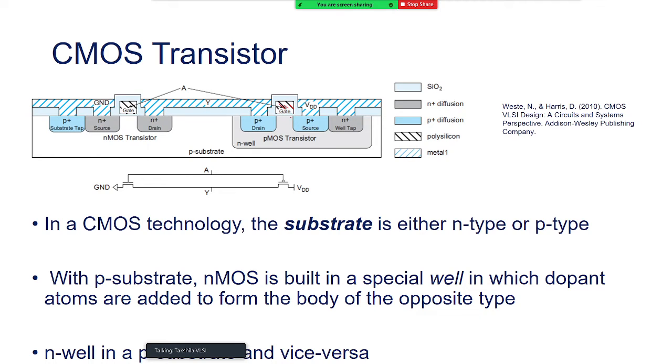Here also I have oxide, and here I have spread the SiO2. It's just for the isolation, because if I have this, I am making sure the source and drain are not shorted. That's what I want for the proper operation. Then again here SiO2, SiO2, SiO2. This is all SiO2 or thick oxide. Okay.